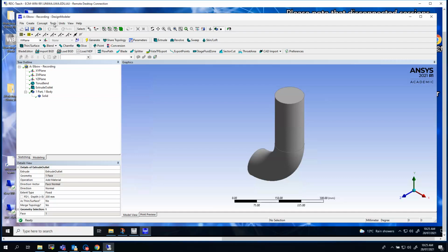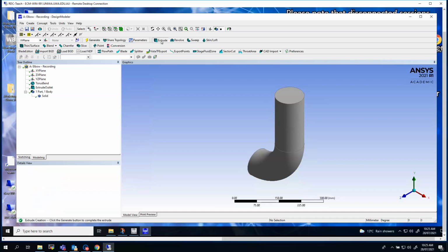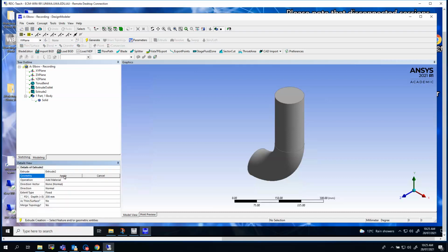All right, next up, we want to extrude the other face. So we can use create extrude again, or if you'll note in this middle ribbon here, there is an extrude operation. Click on that, and we need to select a face. Now, another trick that we can do, we could rotate the face, obviously, but if we know where the face is, what we can do is click on it in its general area, and you'll note that obviously the selector picks the face in front of it.